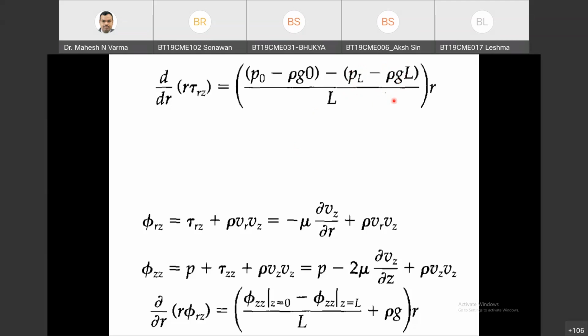Whenever I am measuring the pressure, the gauge pressure will all the time be this pressure plus potential head. So this is the pressure plus potential head at z equals 0. This is 0. This is the measurable pressure at z equals 0, and this is the measurable pressure at z equals L, where PL is a pressure exerted purely by external agency like pumps, and this is pressure because of potential head. So this potential head is higher. So you can see minus L, this is minus 0. Here potential head is 0.